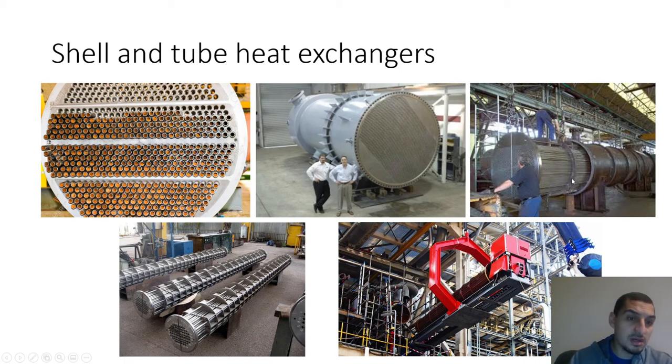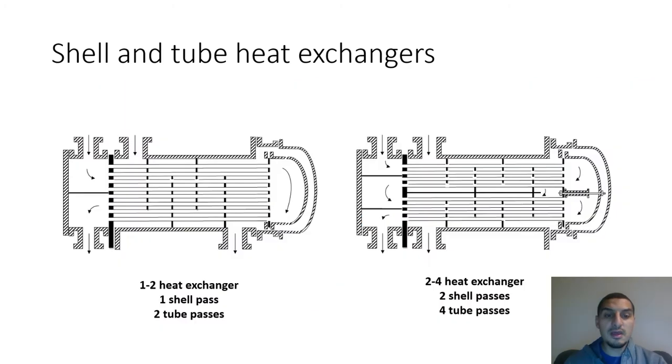You'd see that there are a lot of tubes held with the baffles, and then it's all put inside the shell. And you see here there should be a crane to hold it and make sure there is enough space so you can have all the tube bundle, and then push it inside the shell. This is a routine thing that's done in maintenance, so that it can be cleaned and can be checked in case of errors or problems with the operation.